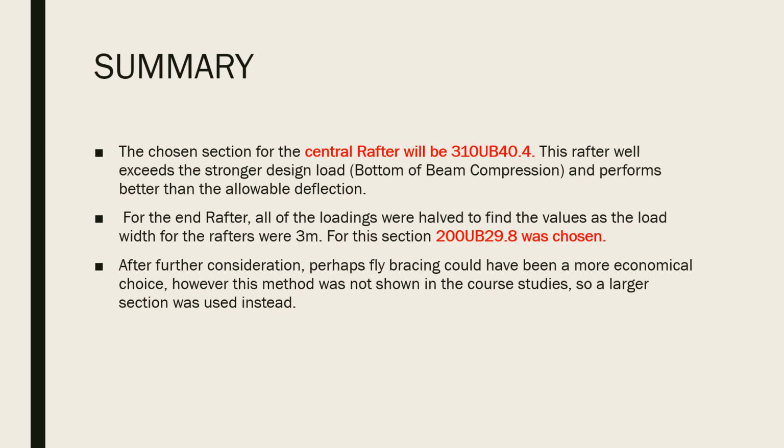We have chosen the section for the central rafter. This rafter well exceeds the design load and performs better than the allowable deflection. For the end rafters, all the loadings were halved to find the values, as the load width for the rafters was 3 meters.